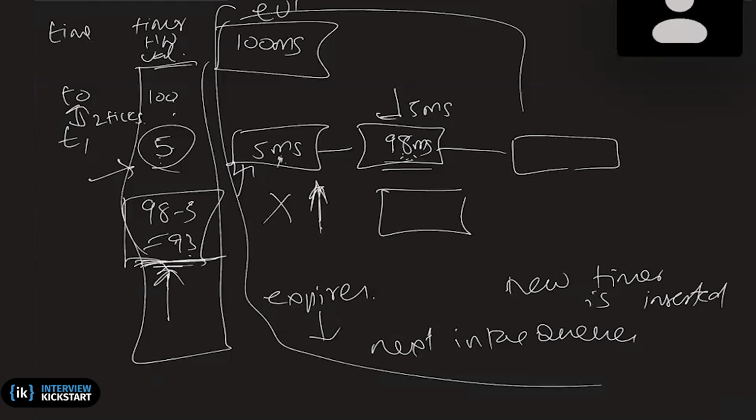Another question. What you said is normally correct. Whenever the earliest deadline event expires, you will go to the next earliest event. But in between, if you're enqueuing a new event, it may happen that it becomes the earliest event. So you may have to reprogram the timer.